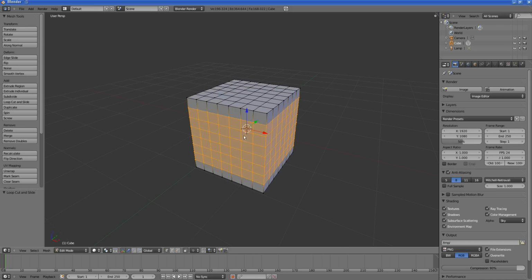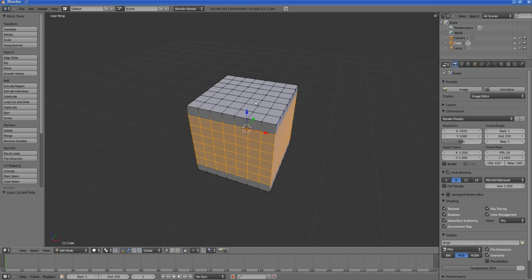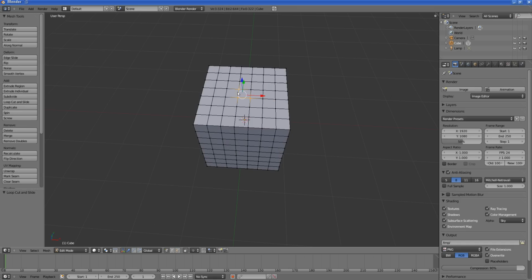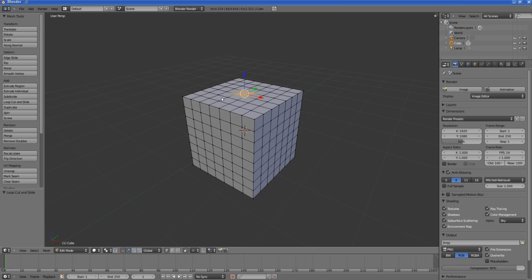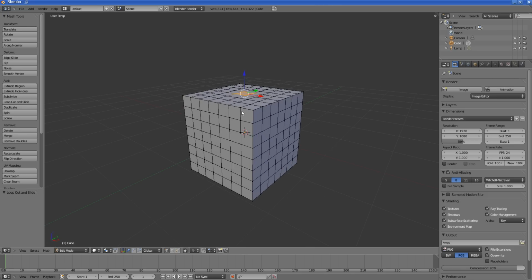Okay, very easy to add these loop cuts now. Now let's learn about mesh editing using proportional tools. Let me select these vertices, shift and right click on the vertices. Now if I move this, G key and move the mouse, only those vertices are moving. Now let me press escape, then go to the proportional editing tool.